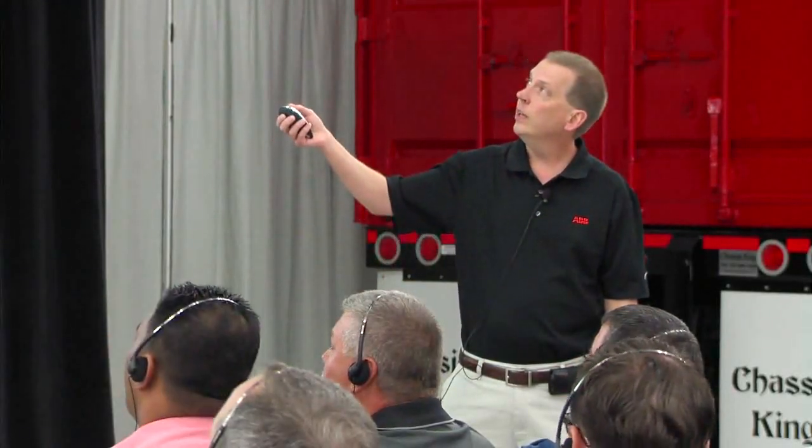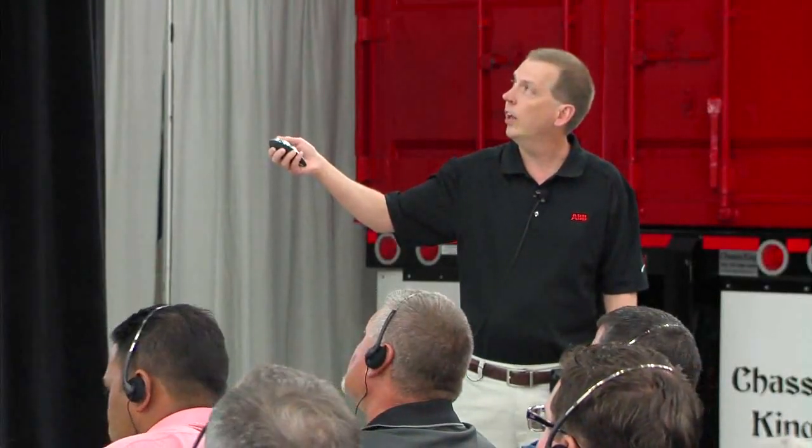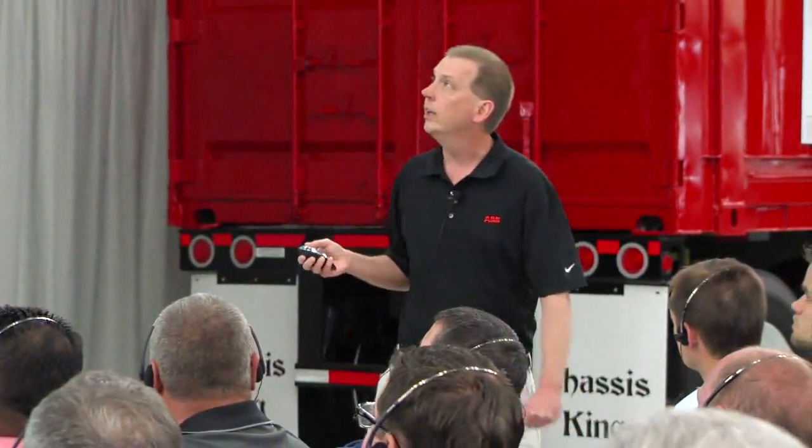That's probably not realistic because we said sometimes you do have to run faster. But if you go back here and say, okay, maybe I only have to run 100% of the time a couple days a year, maybe I can still save $15,000. It's a big number. You understand? Okay, so that's kind of the energy savings take on why you would use an AC drive. On variable torque loads, you can save a lot of energy and a lot of money.